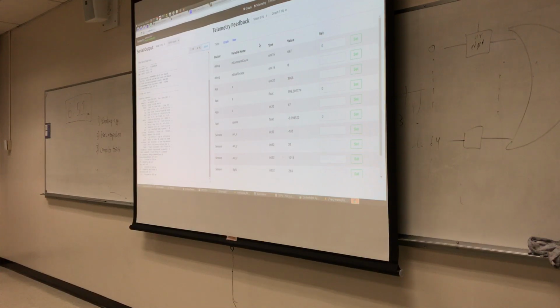So I'm trying to introduce you guys into ways of not using printfs as a means of testing everything, especially in this lab where you can't really do printfs inside of your ISR to make sure it's working or that it got called. You need to do something else, possibly making a global variable, possibly using the FreeRTOS APIs. So keep that in mind. From here, start moving away from doing printfs, start moving into using other systems to get your information.